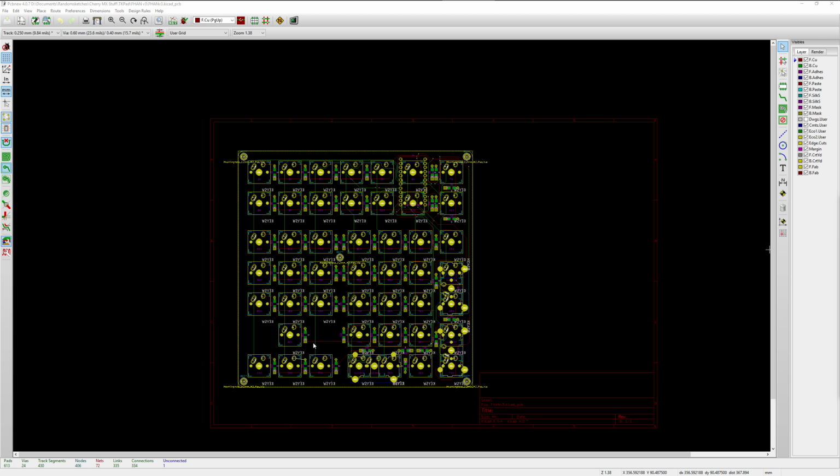Now, when we go up towards the Pro Micro, it starts to get a bit messy, because there's a lot of creativity involved in hopping over and under traces and around. Some are going around the top, some are going through the middle, others are going around the bottom and out the sides. And this is why I didn't want to do it on the actual video, because it is quite a time and patience testing exercise if you're not experienced like myself, because you've really got to move around quite a bit to try and find, okay, where can I go? How do I hop around this?